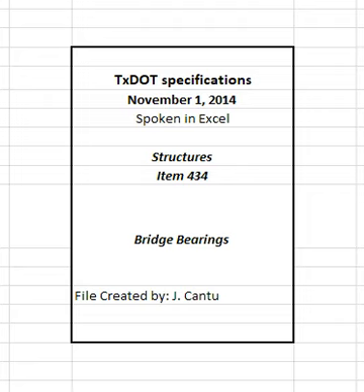Plain elastomeric bearings must be well vulcanized, uniform, and integral units of such construction that the bearing is incapable of being separated by any mechanical means into separate, definite, well-defined elastomeric layers. Evidence of layered construction either at the outer surfaces or within the bearing will be cause for rejection.